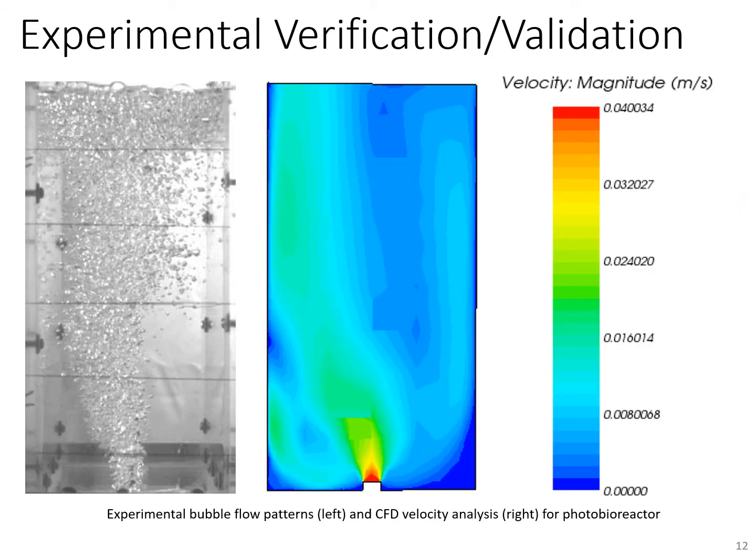Lastly, as mentioned previously, CFD can work as an excellent tool to supplement experimental studies and provide verification and validation of the results obtained. For example, the overall bulk fluid velocity in a column photobioreactor was simulated in CFD and compared to tabletop experiments that were being run in a lab at SDSU. With no light guides present through the photobioreactor, note how similar the fluid flow patterns are between the CFD output and the bubble flow patterns photographed in tabletop tests.